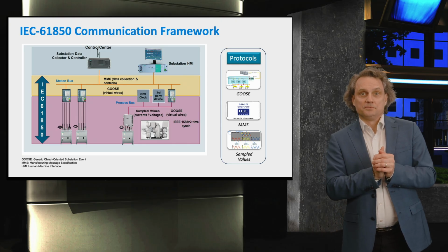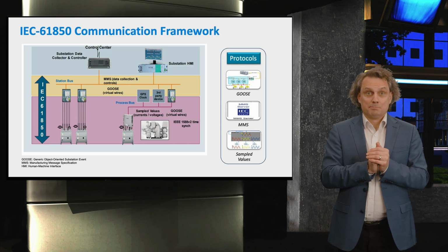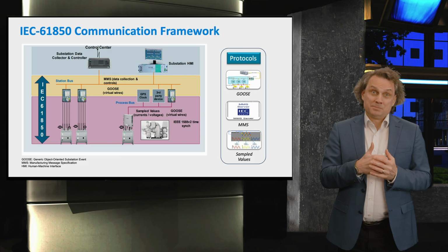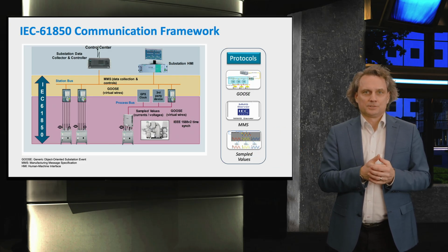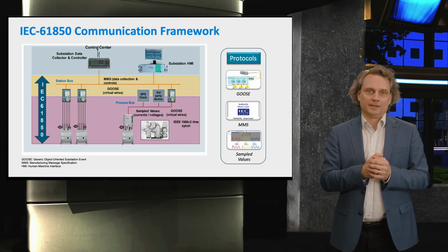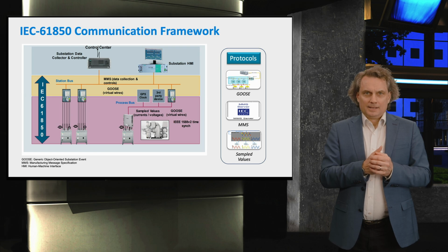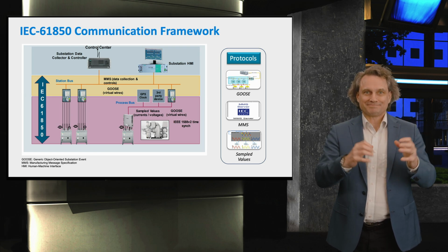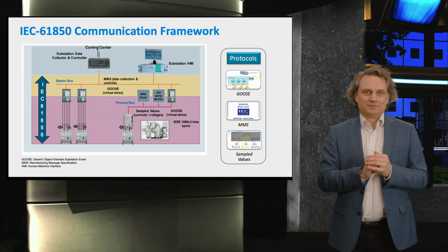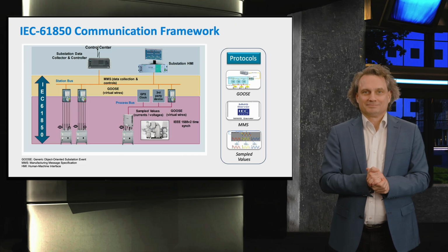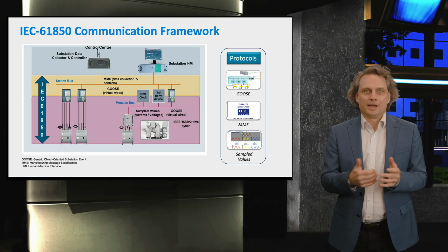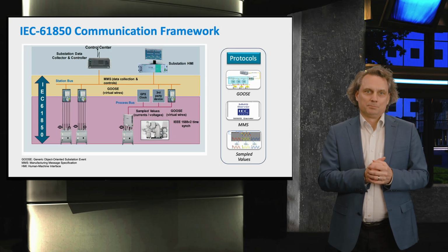In the substation, you very likely also have a source of time. Maybe this is a GPS clock that receives time from satellites. Time can also come via fiber optic connections using time synchronization protocols such as IEEE 1588. Some substations have a little control room, a little shack with a human-machine interface to operate the substation. In most cases, however, the SCADA protocols are routed to the control center where all the switching actions and diagnostic processes can be performed centrally.